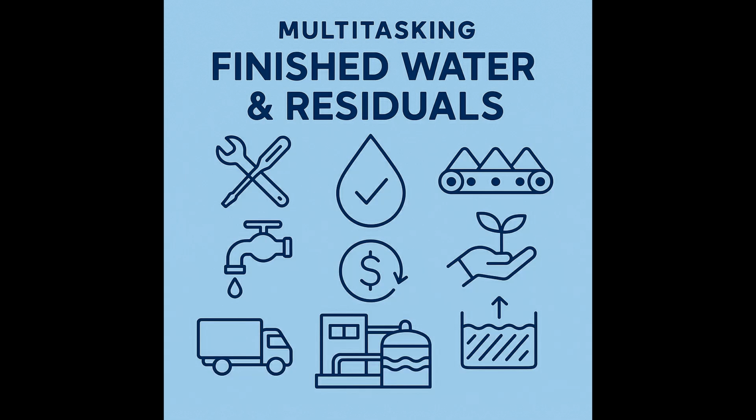They observe things like how quickly the flocs form, how large and strong they look, how quickly the solids settle out, and sometimes they'll even try to simulate dewatering on a small scale, like squeezing the sample in a filter paper to see how clear the released water, the filtrate, is and estimate cake dryness. It's a relatively quick and inexpensive way to troubleshoot problems or screen new polymers before trying them full scale. Saves a lot of chemical costs, potentially.